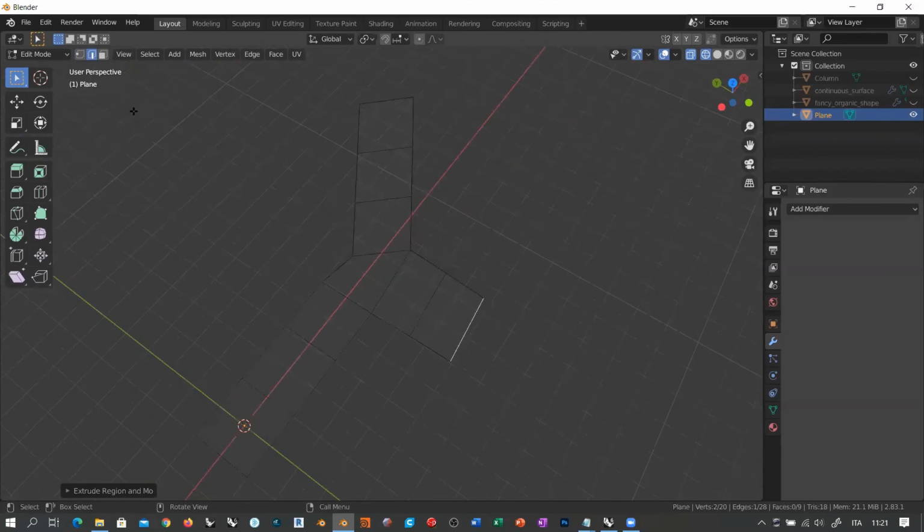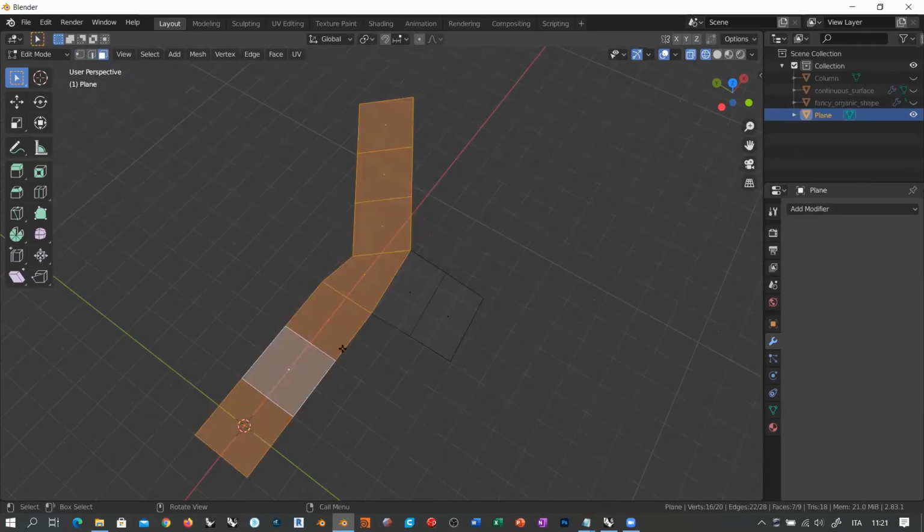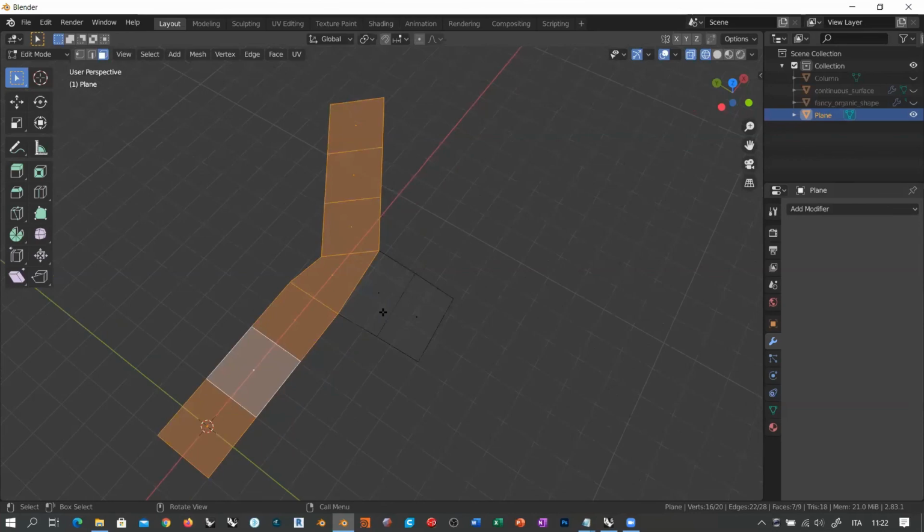What happens when I switch to face selection and I alt click on this cross edge? You see that only one part of this mesh gets selected because the loop only runs in one direction. So this bifurcation that we have here is not taken into account by this loop. We must avoid these kind of things, okay? So how can we, for example, make this situation a little more regular, so that we have 2 loops that run in this direction and absorb the whole mesh?